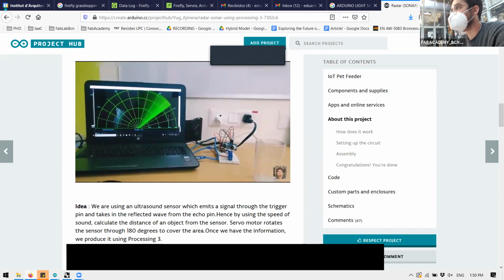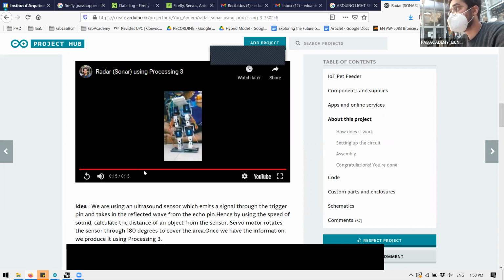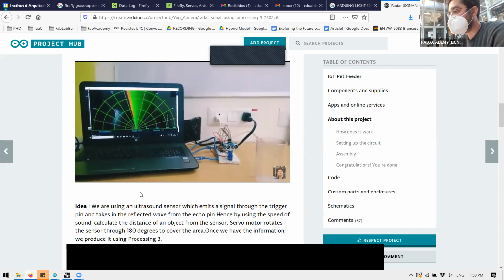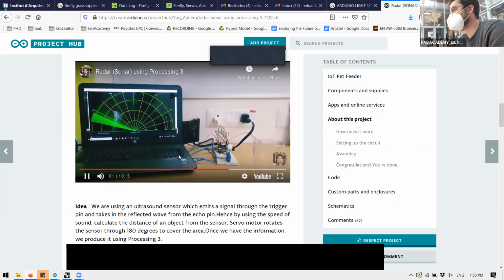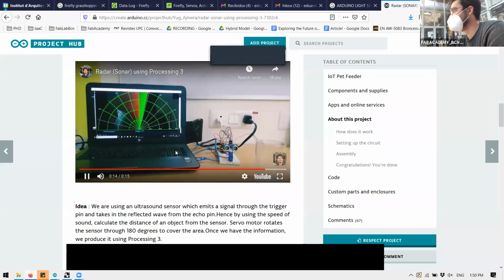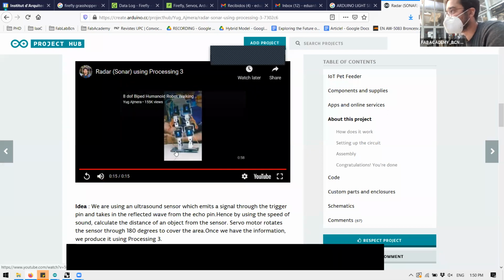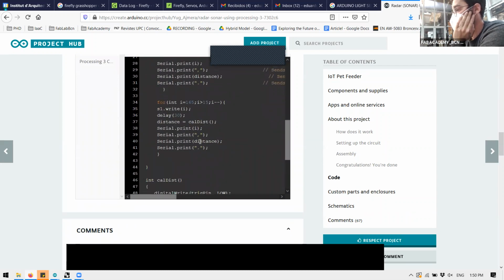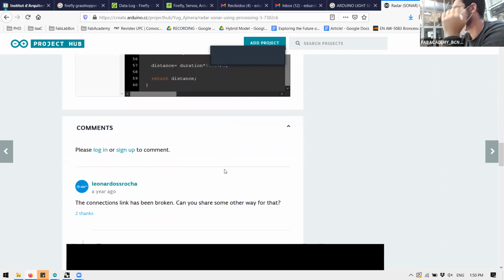Oh, I see what you meant. Now it's all about how you extract the data and take from it. Exactly, you want to recreate a room. The sonar is the least accurate sensor ever, but conceptually it's the same. The difference is that the moment you have 3D, everything gets messy, and it also depends a lot on the distance. One degree at 1 centimeter doesn't make a difference, but 1 degree at 50 meters makes a huge gap in the prediction. This uses exactly the same approach: it serial prints the distance, and you are reading that, and we have the virtual representation.